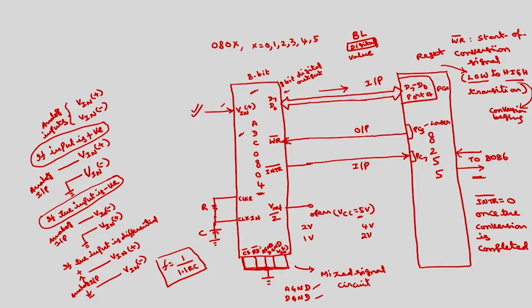So what is the control word for this? If I take the control word register, the last bit is port C lower, this should be output, 0. Port B we are not using, I am using it as output port. Mode selection for port B, I am using mode 0. Then port C upper should be 1 because we are going to use it as input port. Port A has to be used as input port, so this should be 1.